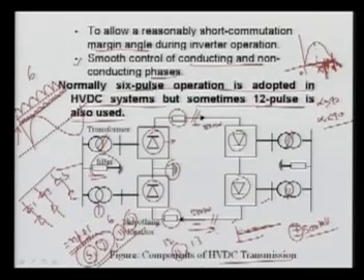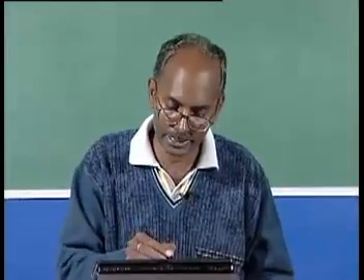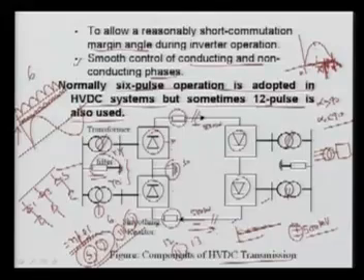Normally, if you are using a 3-phase supply system and you have a bridge converter here, for example, one bridge converter, and here we have another bridge converter. Normally this is, let's suppose, star-star. Here, if you have a star-delta connection, then there is already a phase shift of 30 degrees, and you are adding the voltage. Means 2 6-pulse converters connected by star-star and star-delta, and if you add the voltage, automatically they will provide the 12 pulse.